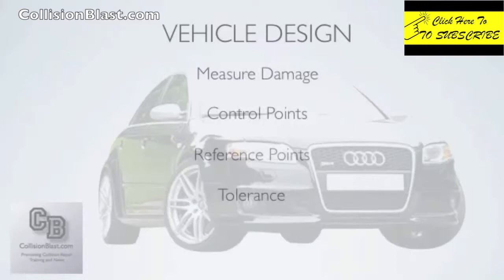So when we do get some frame damage, we have to think about how to measure this damage. First off, I'm going to talk about control points. What are control points, reference points? Well, control points are where the factory put these pieces together. The robots have to grab these pieces in certain areas, and they hang them in jigs, putting it together. Those points where these machines grab are designed in just so that they fit into the jigs. So that's control points.